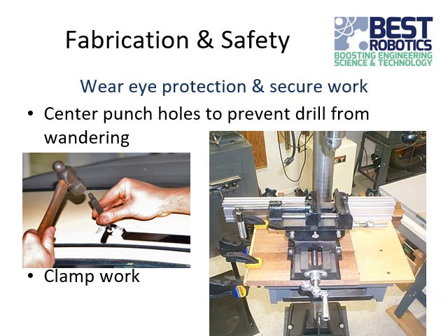For drilling, and this is especially true if you're using a hand drill, it's a good idea to center punch your holes ahead of time. What that does is put a little divot there that the point of the drill can rest in when you get started. Otherwise, the drill has a tendency to wander, is what they call it, or walk around a little bit before it really starts digging into the material.